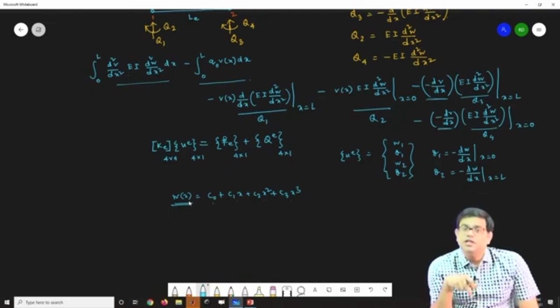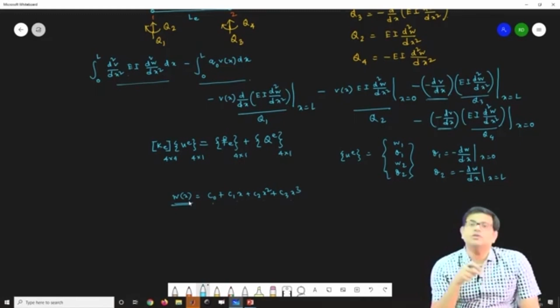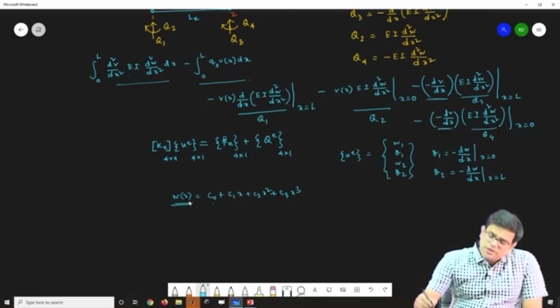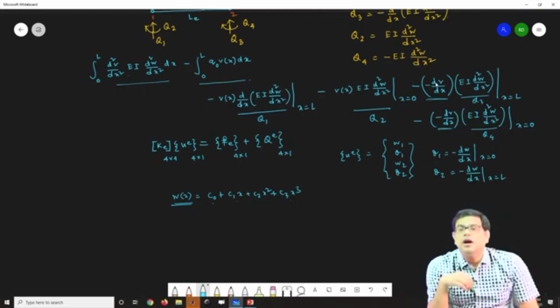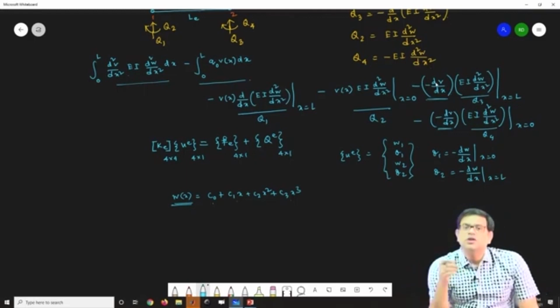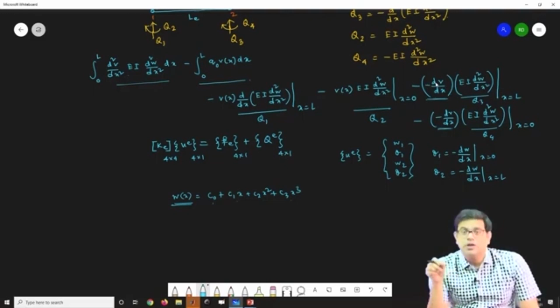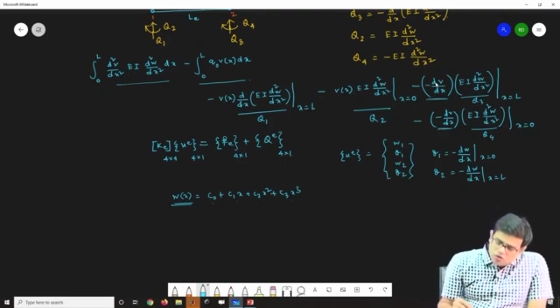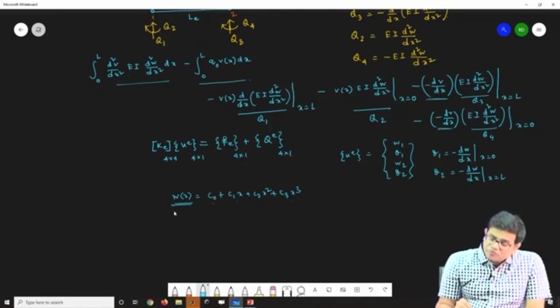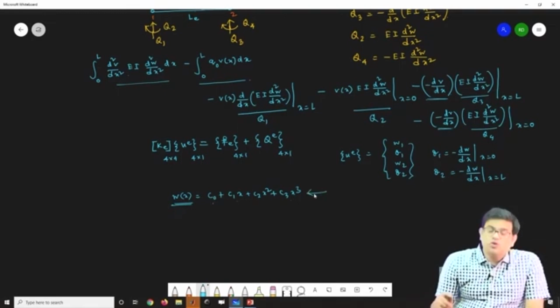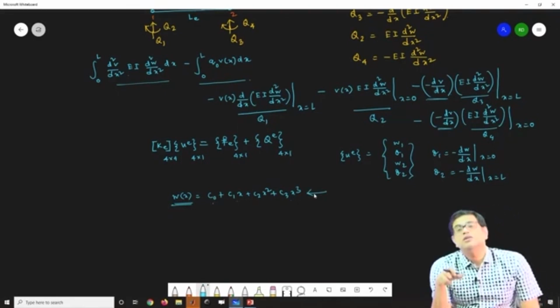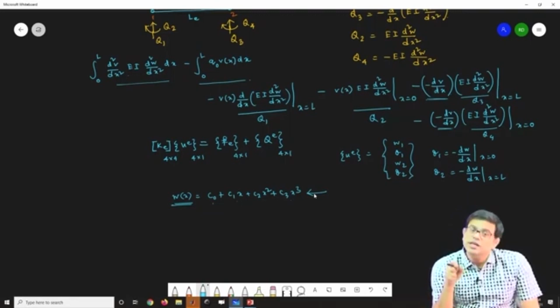But in the case of beam shape functions, this is a requirement, because the interpolation has to represent the degrees of freedom at a particular node, and it has to cancel at the other nodes. The cubic Lagrange polynomial doesn't assure me that the slope, or first derivative, will be interpolating and continuous.